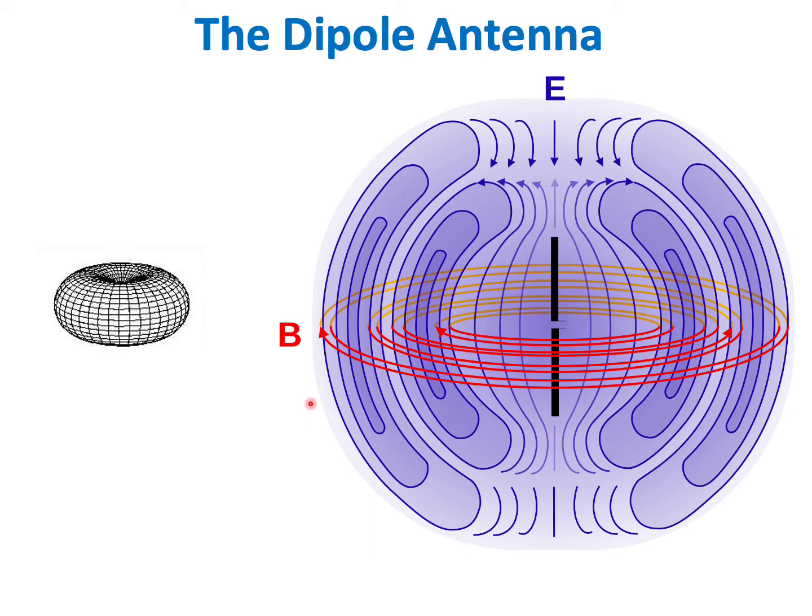So that radiation pattern, as I said, it's a torus. If you look over here on the left, that's what it looks like. But this is for a dipole that's vertical. Previously we were just imaging our dipoles horizontally. Here we have a vertical dipole, so you can see it a bit easier. Here are the two halves of our dipole oriented vertically, and the torus of the electric field around it. This shows the torus a bit better, and here you can see the vertical dipole inside that torus. For our case, with the horizontal dipole we were looking at, this torus would be rotated 90 degrees.